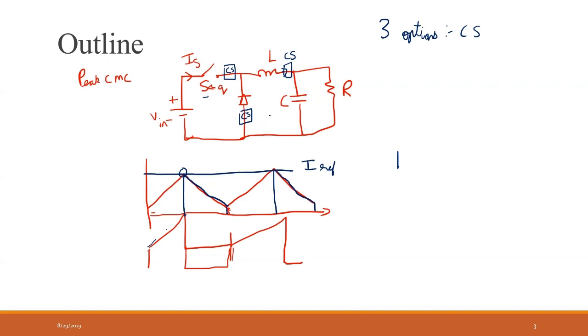It depends on the application and various things. All this will be taught in, I think, week 7, where we talk about the various sensors available: high side current sensing, low side current sensing, full current sensing of the inductor. If it is not possible to sense the complete inductor current and we want peak current mode control, that is, we want to control the peak value of the inductor current, then we have to use the high side current sensor.